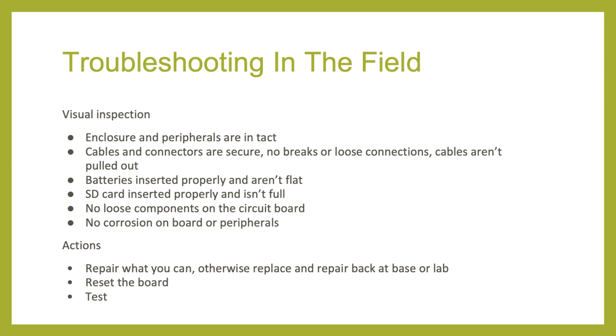Then we'll check the cables and connectors are secure and haven't been knocked out or torn or damaged. We'll check the batteries are securely inserted and aren't flat, and the SD card is still inserted properly and isn't full. And we'll also check there's no loose components on the actual circuit board itself. If we have a multimeter with us, we'll check the battery voltage and the power supply voltage. We'll also do a visual inspection for any corrosion on the board or peripherals. If we find any of these, we'll swap it out or fix it if we can. Then we'll reset the board and test the system is working okay.